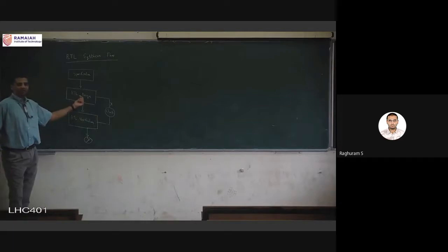Okay, so we have added this one step here, which is your RTL verification, and this is traditionally done using your test bench. That is, you are writing some Verilog code and you write another file called a test bench, and in that test bench you instantiate this design and you give it different inputs in random order or in any order you want. That particular step is called RTL verification. And once this is done and you're sure it is correct, now we go for the